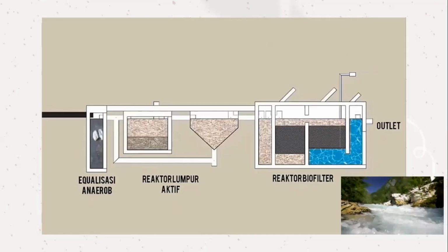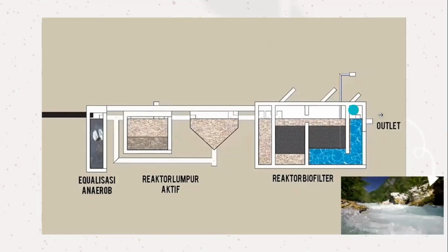The runoff water flows into the final settling tank and then flows into the chlorine contactor. It is for the disinfection process to kill pathogenic microorganisms. Effluent water that comes out after the chlorination process can be directly discharged into rivers or a public canal.